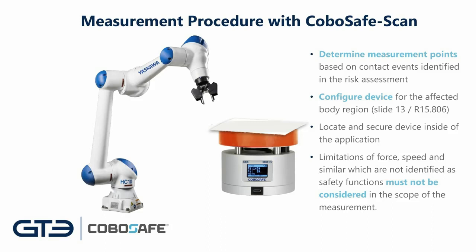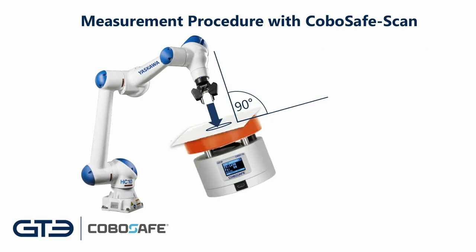One most important point is that when you want to measure, you have to ensure that only safety functions are enabled. The measuring system is a single axis force gauge, and you have to ensure that the measuring plate of the force gauge shall be positioned centered and perpendicular to the path of the robot system.